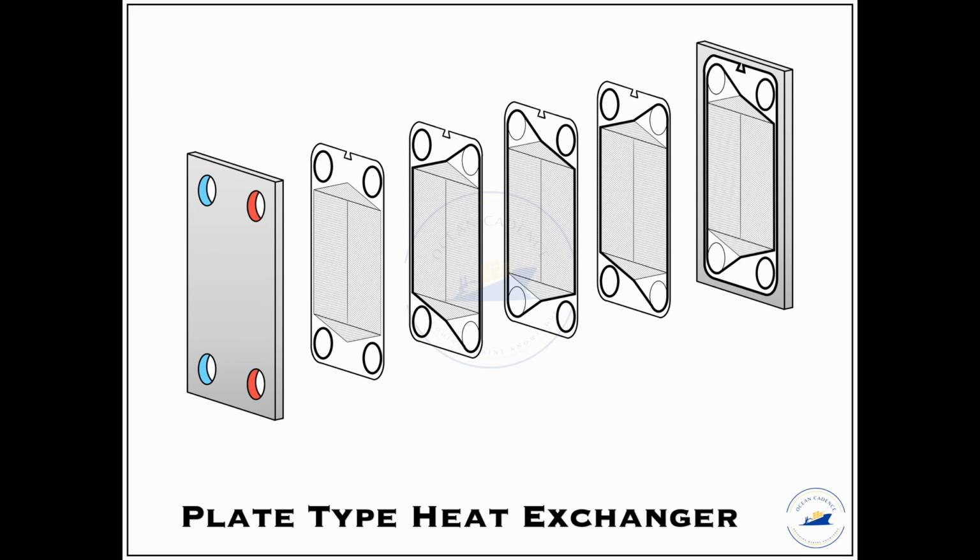Now, the plate type has been developed because of its higher efficiency, in terms of the fact that these heat exchangers have a lower downtime. They are much easier to handle, much easier to isolate, and much easier to clean, and they have a higher performance efficiency as well.